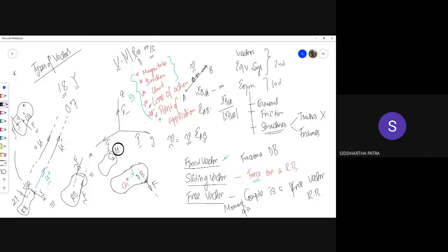the same. The crucial thing is that while you are taking these forces F and F, you can change the direction. Okay, you can change the magnitude and the distance, inversely proportional. Only thing is you cannot change the plane of the forces because the moment has to be perpendicular to that plane. So the moment itself is a vector. How is that a vector? We'll see that in a later stage, and that has to be perpendicular to the plane. Okay, so the only thing that you cannot change is the plane of the two forces.